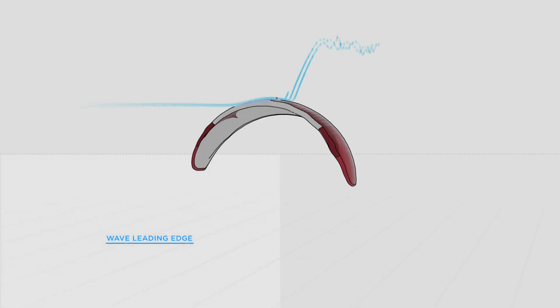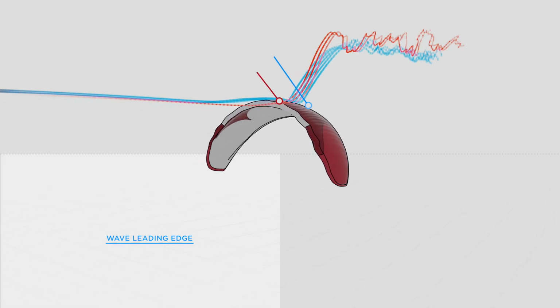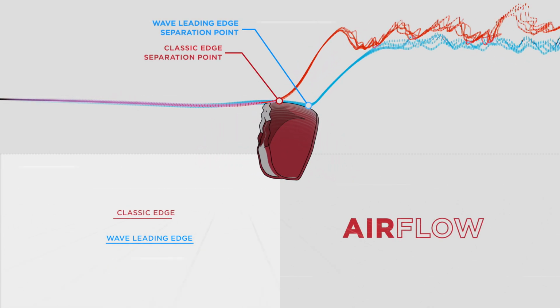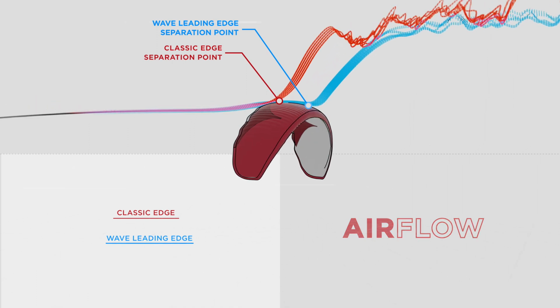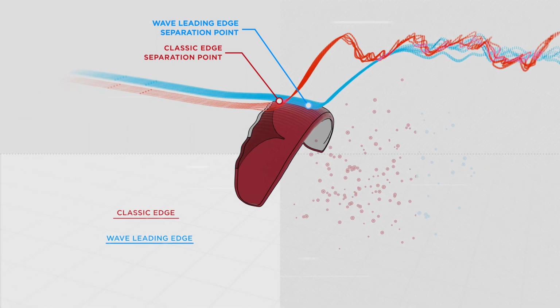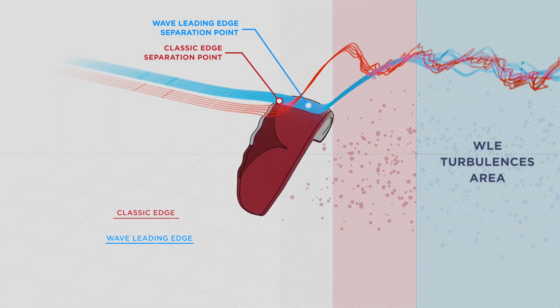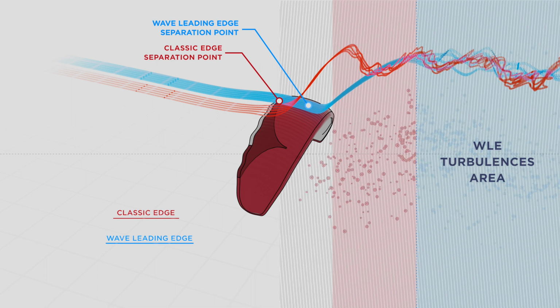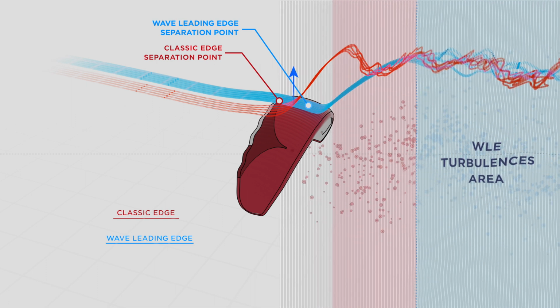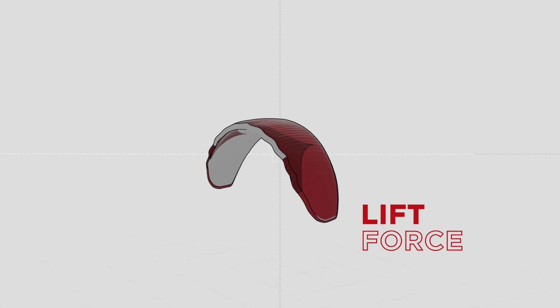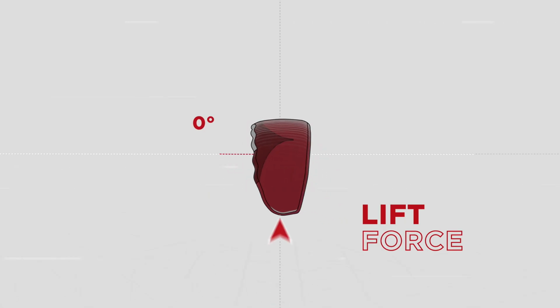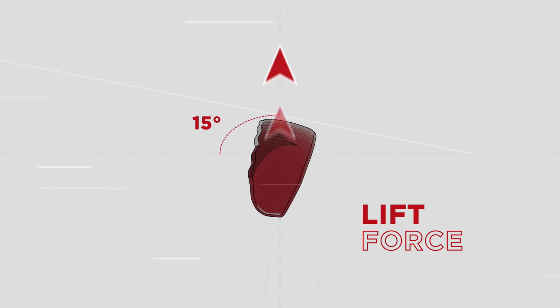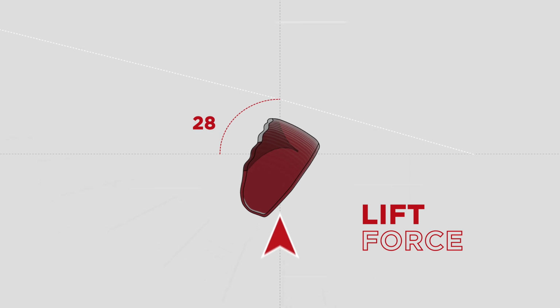At the leading edge, normally airflow is coming, and then right after you get the separation and create the turbulence. But with the tubercles, because airflow is coming in the middle of these tubercles and brings all this turbulence more to the backside of the canopy, your stall speed is quite delayed, and because of that you have more lift. But the problem is that when the angle of attack is too high, then the pressure underneath of the wing is still high, but the pressure difference between the upper and lower surfaces becomes small, which results in the reduction in the lift force.